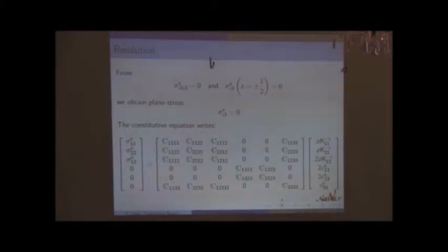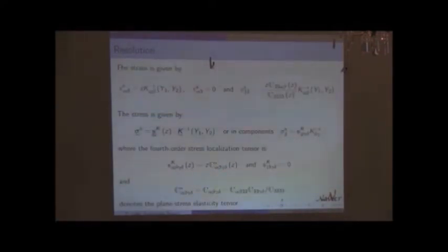If you multiply this line times this line, you can express the normal strain as a function of the in-plane strain and directly as a function of the curvature. So I just write this on the next slide. I just recall that the in-plane strain is the linear distribution of z times the curvature tensor. The transverse strain is zero, and the normal strain is related to a Poisson effect, linearly distributed through the thickness. So the out-of-plane displacement won't be zero.